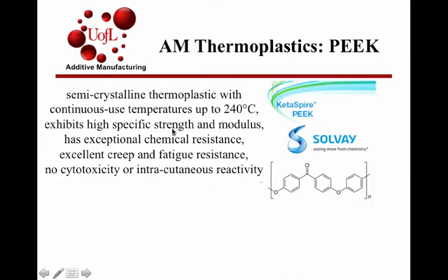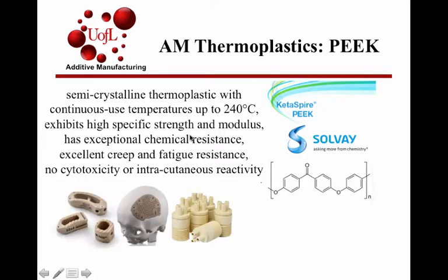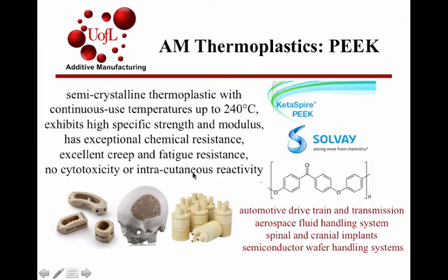They have very high specific strength and modulus. Relative to their density, their strength is very high. They also have a very high chemical resistance. One of the notable attributes of this material is their inertness in a biomedical environment. It does not display any toxicity to the cells. It does not react with them in any particular way either. These attributes make PEEK very useful for medical applications.